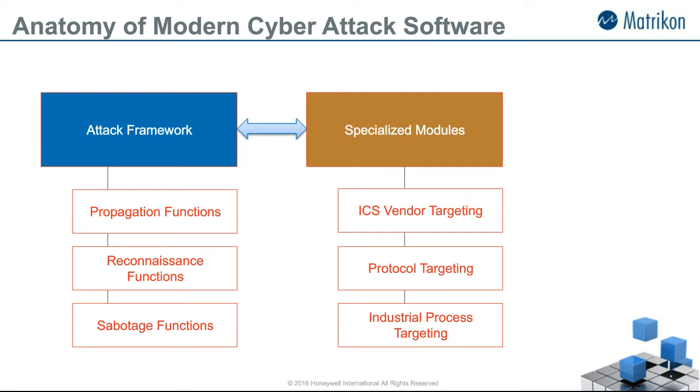So you've got this flexible framework, and then you get experts on the bad side who come in and start targeting either specific vendor equipment, or they start targeting how to implement and use various protocols in a legitimate way, but again, to start actually targeting the process that's relying on those protocols in order to do something. In this case, I'm using the Ukraine example. There are various power station or power industry specific protocols: the 60870 protocols, both the 101 and 104 standards, 61850, and OPC DA also was used in this attack. Hence the connection to our presentation here, talking about OPC vulnerabilities.